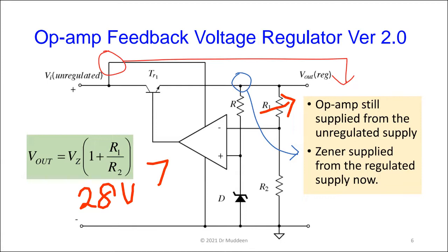But of course, my unregulated supply here is only 20 for the one that I use. So I could get all the way up to, well, within a couple volts of 20. But certainly I could get from 7. Yeah? So that gives you an idea of this sort of range. The other approach that sometimes is taken is to leave these two fixed here and to insert a variable resistor in here. Okay, so this gives you a little more tolerance over it. It would never go down.